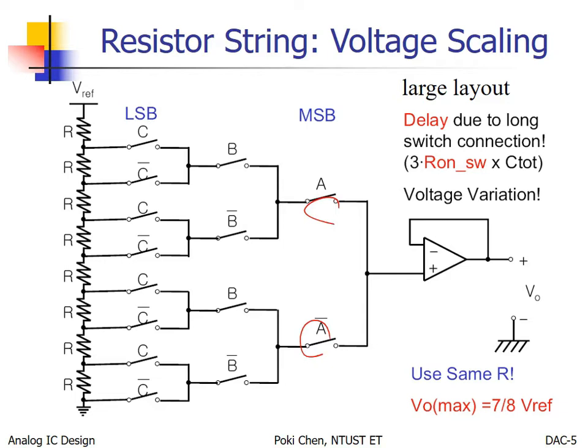In analog IC design, usually we have a transmission gate. I told you already, one PMOS and one NMOS connected in parallel, and the control signals are complementary. If I'm 1, you are 0. If you are 1, I'm 0. That's it, to turn both transistors on or off.